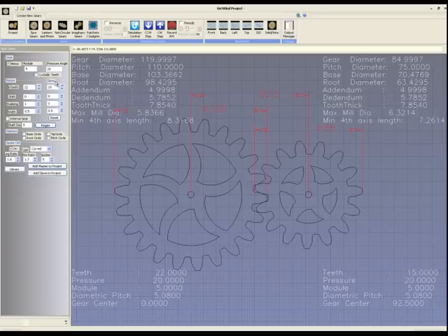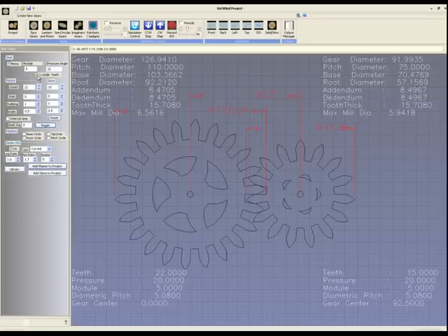We have a checkbox for cycloidic teeth. If we check it, you can see that you go to the older style of cycloidic teeth. These are commonly used in clockworks. At the moment, the only cycloidics that you can generate are the standard module cycloidics. The parameters underneath these checkboxes, which change things such as the profile shift, stubbing, and tooth width, are not used in epicycloidic teeth. The size of an epicycloidic tooth is dictated by the typical module settings of your spur gear.